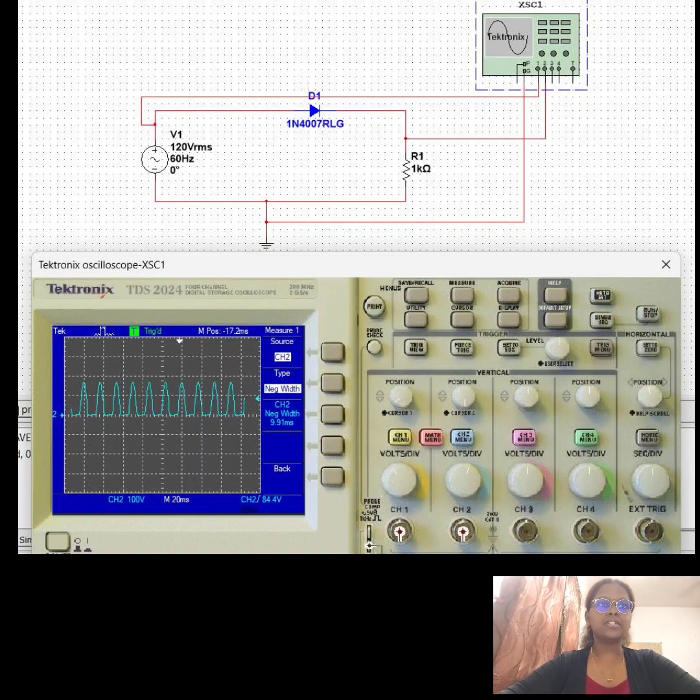To convert AC voltage to DC voltage, half-wave rectifiers are employed. They can be built with just one diode. As a result, as seen in the image, the output waveform lacks a negative cycle. Low voltage is produced using half-wave rectifiers. This demonstrates how diodes only let one direction of current flow.